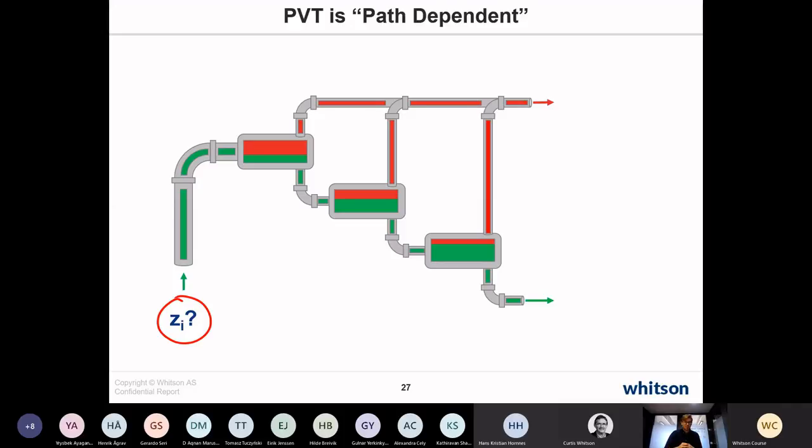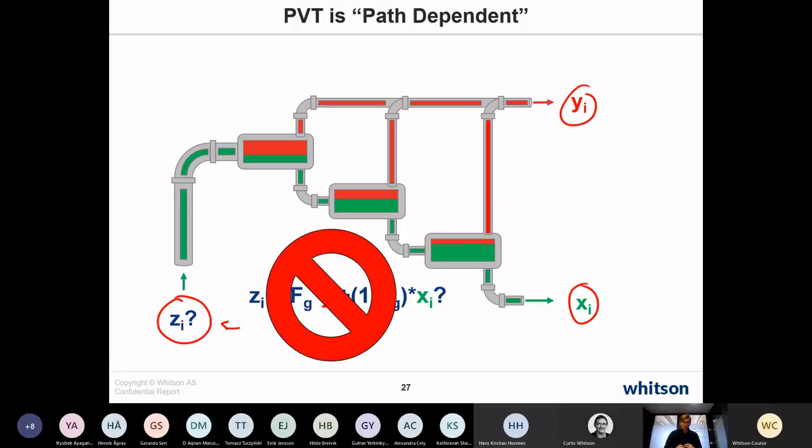This is a 3-stage process, and the 101 mistake in this case is if you only take the final gas and oil compositions and directly recombine them to try to get this total well stream composition right here. And we'll talk more about this recombination equation when we talk about composition. But this is essentially not what you like to do.